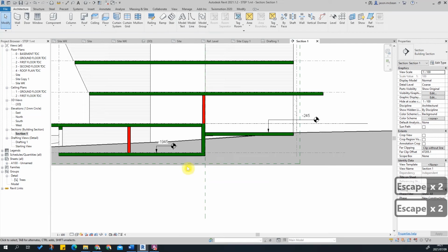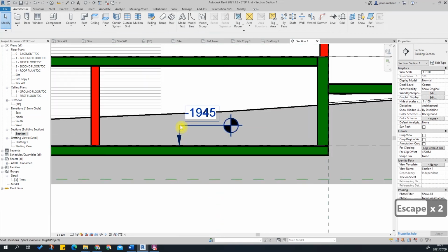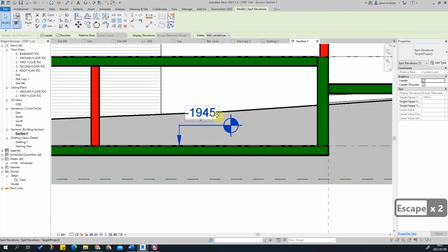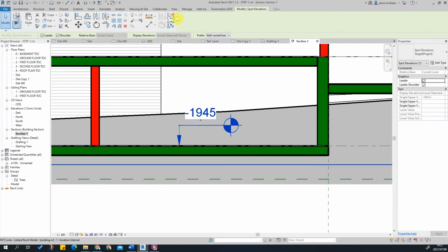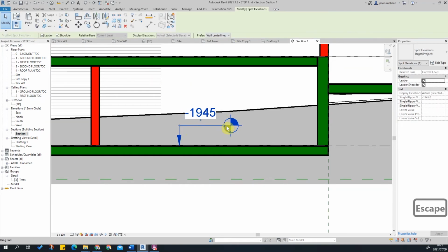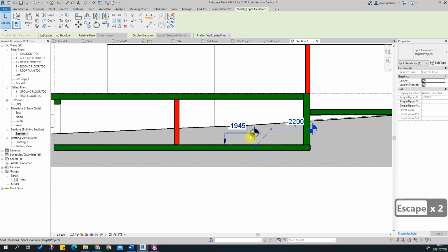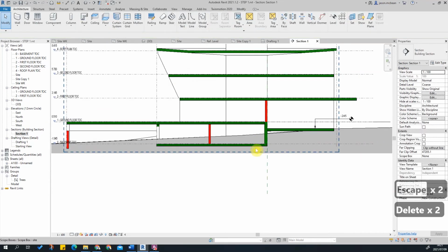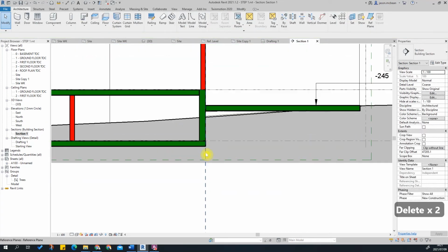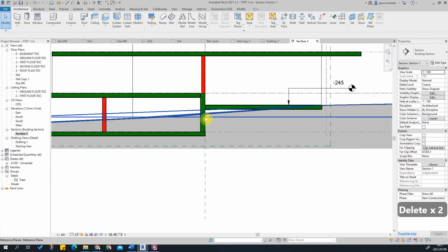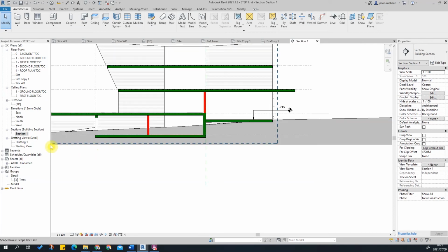Okay. We can make it a bit lower. So I could actually say pick new host. So select this level, and I can simply tell it to pick a new host. Okay. So here, spot elevation, it should ask me to pick a new host. We can just say create similar. Yeah, minus 2,200. So if I made it minus 200 and then I used a pad, it'll work well. Okay, so from here, it's going to start changing to the front there.